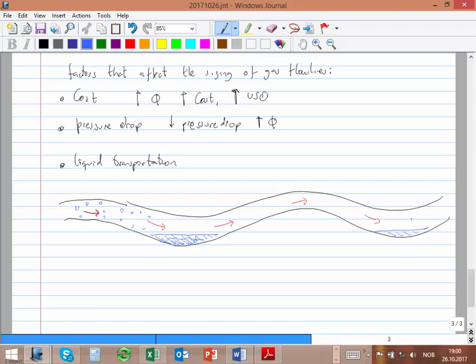And then when I have that, first I have reduced flow, so this creates a delta P, and then it might become a day that actually I have pipeline blockage. So these low points can create increased delta P, increased pressure drop. They can also create pipe blockage, just because the liquid goes up to the whole level and then the gas cannot go through, and can induce corrosion.